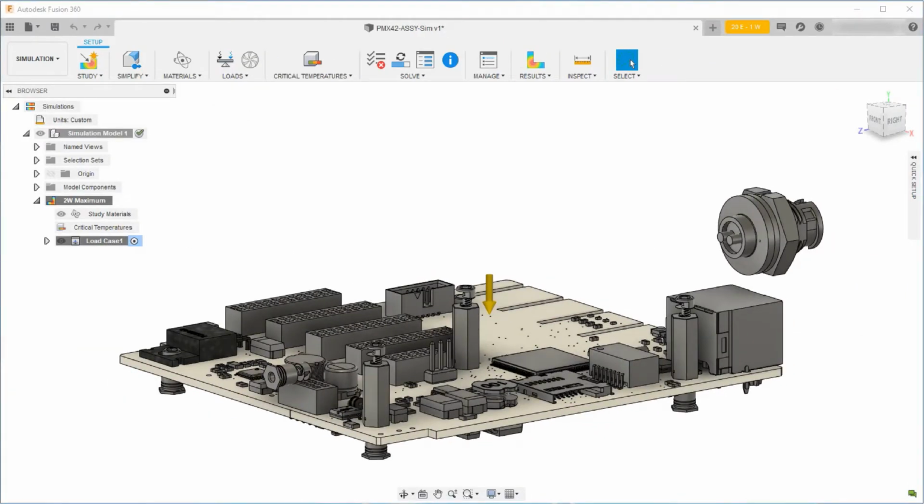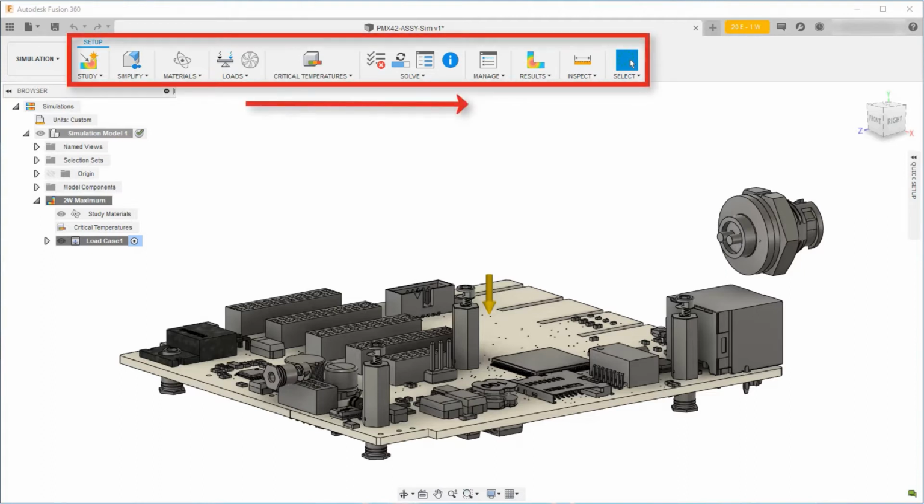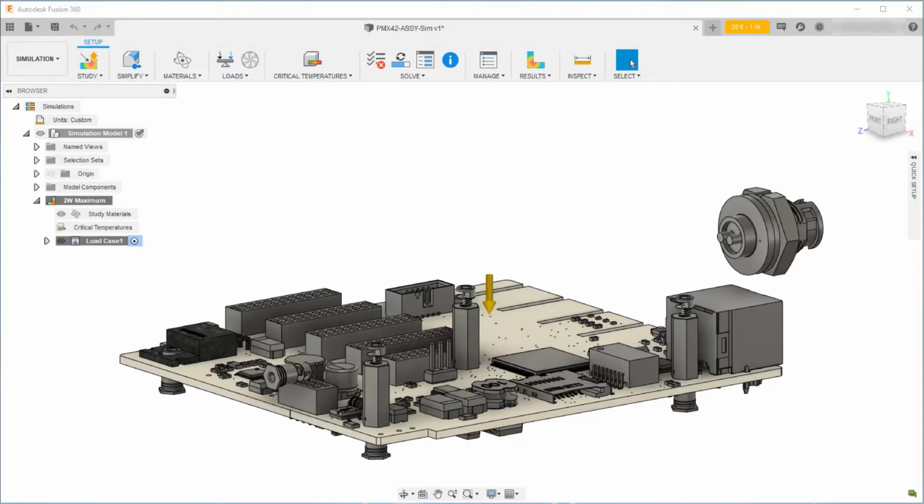As with everything in Fusion 360, you work your way along the ribbon from left to right. Often you can speed up a simulation analysis by manually removing details from the model components using the tools in the Simplify environment. In an electronics cooling analysis, this simplification is done automatically by the solver. The air volume around the board is also built automatically.